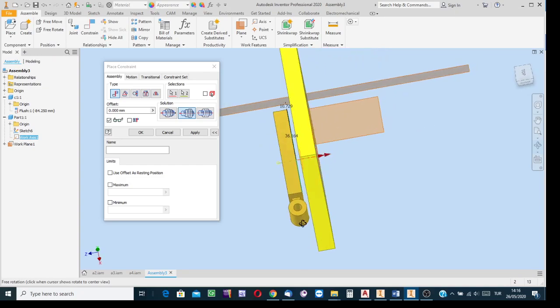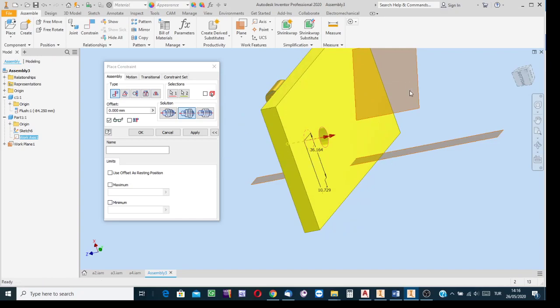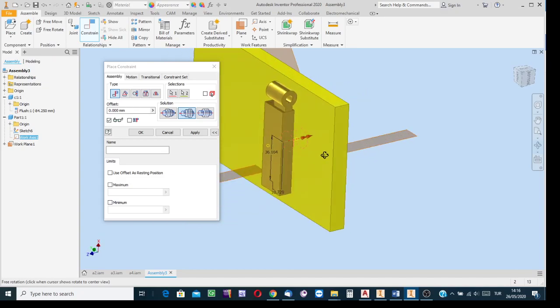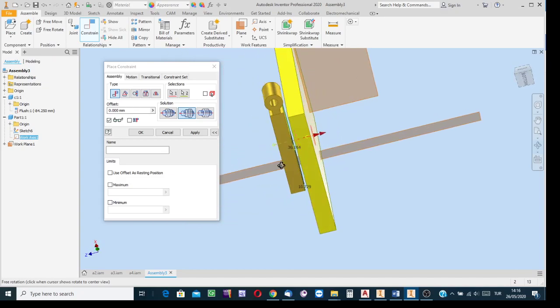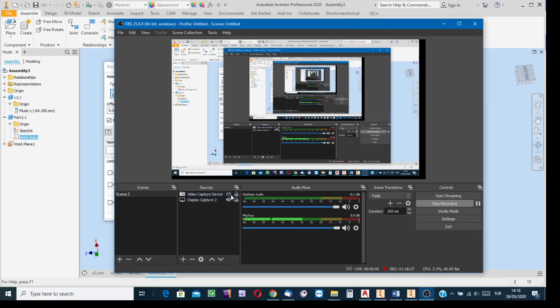Okay, the last part of this record: as I said, if necessary, you can use work planes to position the components with respect to each other, or a work axis. If axis is not defined for one component, then create a work axis, and use that work axis to bring the component into alignment with the other one, which has an axis or work axis. Okay, now finally ending this video record. I hope I managed to provide valuable complementary material, my dear students.